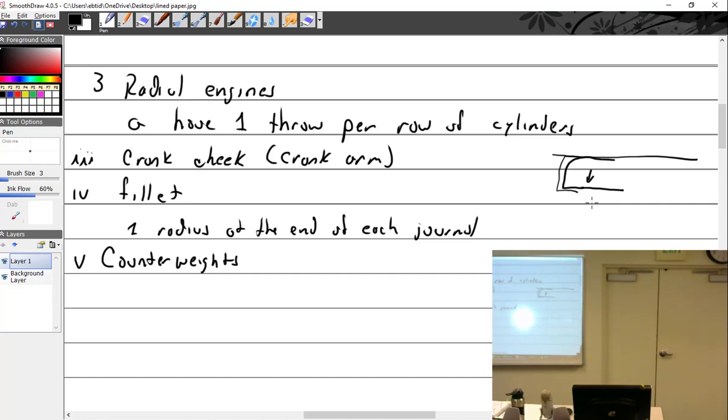There's a space in between those. And if you don't get the snap ring in its groove all the way, then it hasn't popped out and expanded. So there's actually instructions, especially Lycoming, where they want you to pop it out and then measure the distance in there. Continental too. I think that was the Continental one. And you have to measure that distance and make sure that you have enough distance. If you don't, that means that it's not there. Because once those things come apart, they really come apart well, and they fling all over the place.